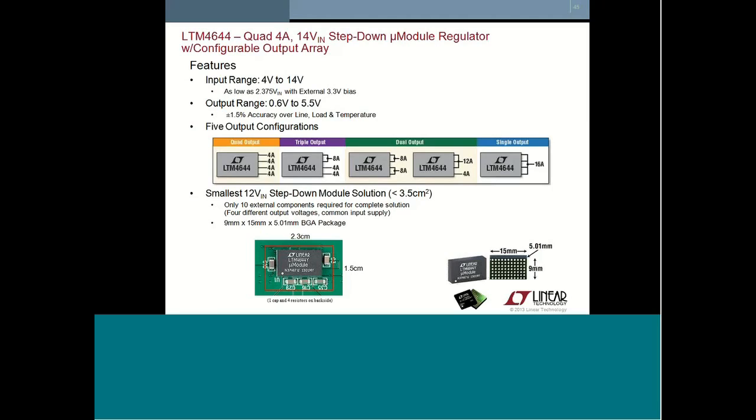4 channels have fully independent inputs, outputs, enable, and power good pins. However, to support current sharing, all four do operate from the same clock, 90 degrees out of phase, which also reduces output ripple.